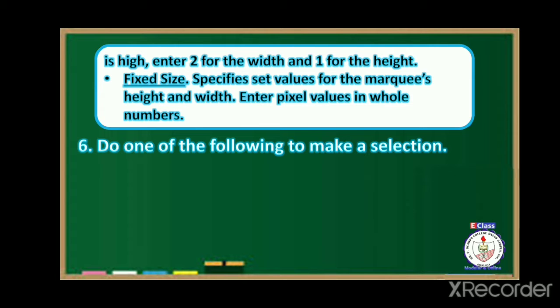And here are quick tips. To reposition a rectangular or elliptical marquee, do the following. First, press the mouse button and drag to create the selection border. Second, hold down the space bar and continue to drag. Next, if you need to continue adjusting the selection, release the space bar but keep the mouse button depressed.